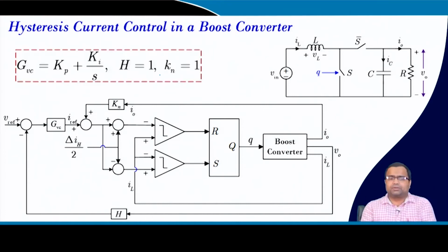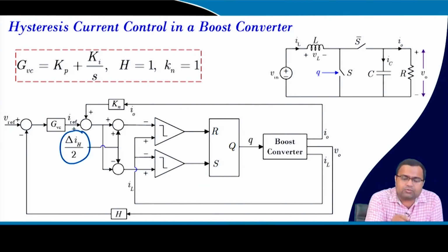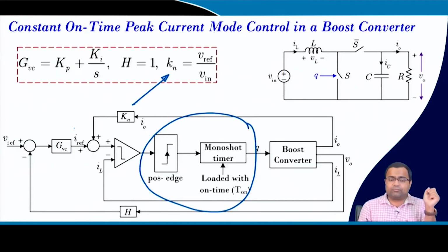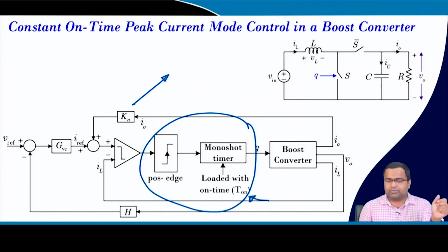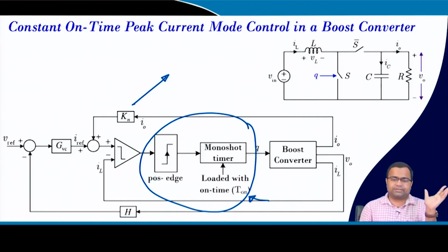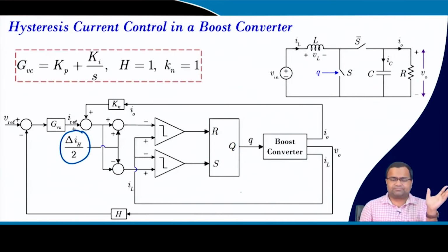Okay. So, with voltage hysteresis control, by adjusting the hysteresis band, we can control the switching frequency. For the previous one, we can control the switching frequency by adjusting the on time, and by adjusting the off time. For fixed frequency control, it is already fixed frequency, the time period is fixed. So, that means we can implement all this logic.